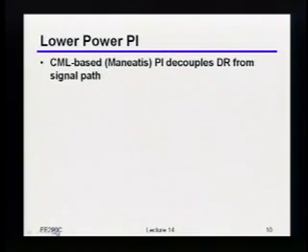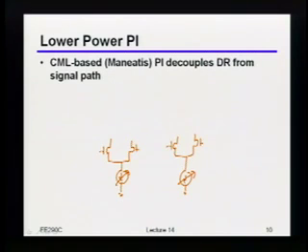Bingo. That's exactly right. So the beauty of CML logic is, and let me give myself a little bit more space, I have those two current sources, right? And basically, I'm not changing them all that fast, so I don't have to be at really high speed when I build those current DACs. Obviously you don't want to be sloppy, but I don't have to worry so much about the speed. So indeed, the way you will typically build these phase interpolators is with some current steering kind of logic, because it really just decouples the high-speed signal path from the high dynamic range.